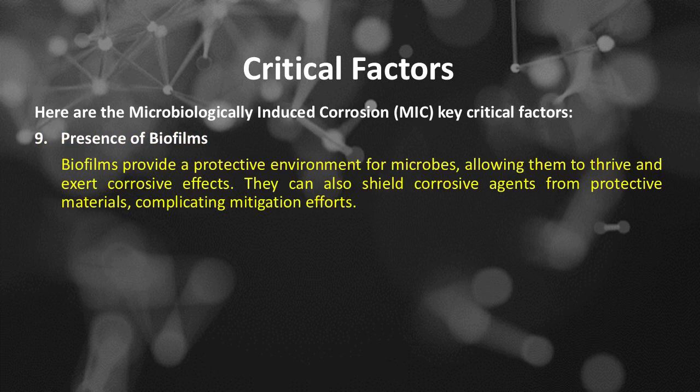Number 9 of the microbiologically induced corrosion, or MIC, key critical factors is presence of biofilms. Biofilms provide a protective environment for microbes, allowing them to thrive and exert corrosive effects. They can also shield corrosive agents from protective materials, complicating mitigation efforts.